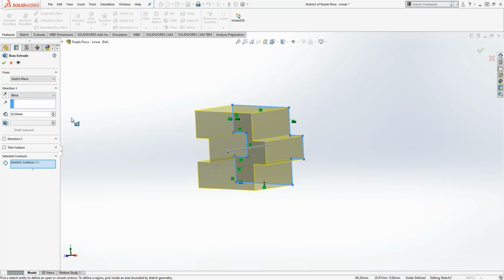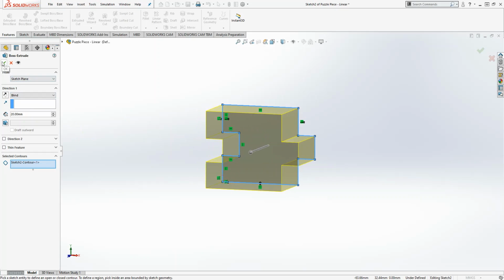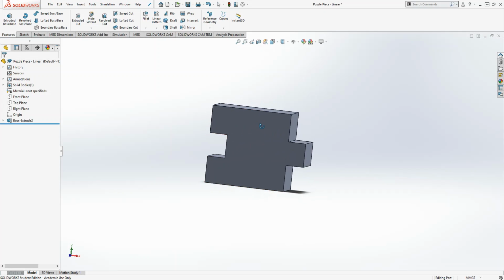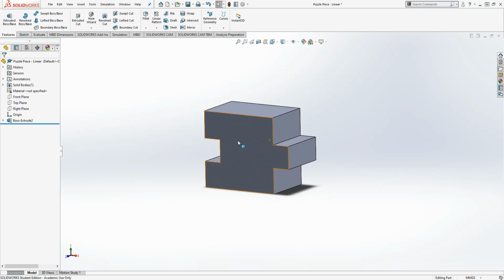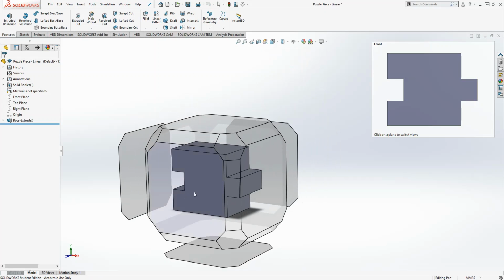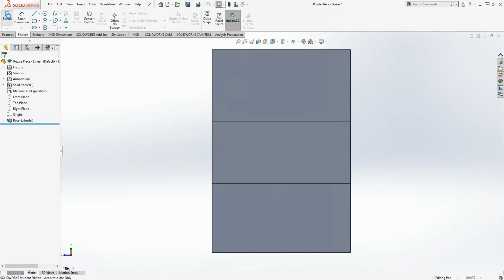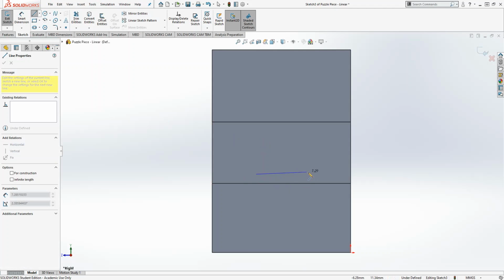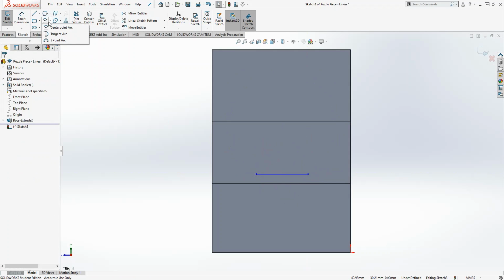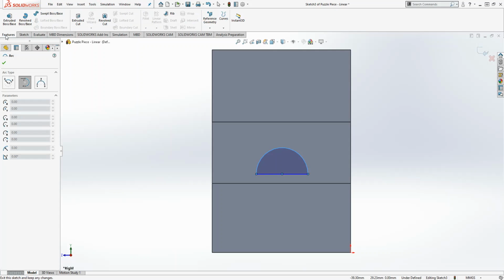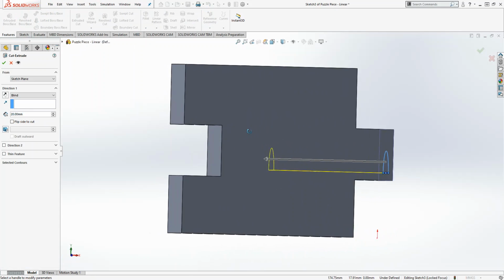So if I take this document that I have with my sketch pattern that is completely grayed out, it's complete, it has all of its bounds properly defined, I can click on it to select the sketch, and then go to Features. I can also go to the Feature menu and select the sketch. Either way works. You're just taking all of those lines, that sketch that you've created, selecting it, and then you can go into the Features menu to begin extruding this into a physical mass, a part, and actually begin to have a 3D model instead of just this flat plane outline that we have.